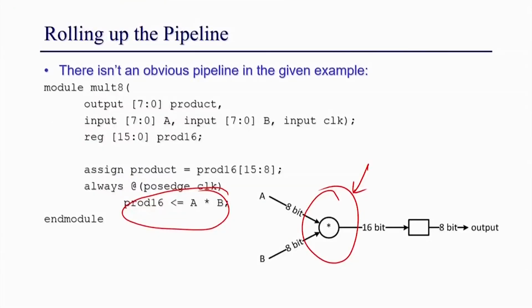This is also possible, and sometimes you have to do this kind of optimization just to achieve your target area, because maybe on your FPGA target your design does not fit. You need this kind of small change in your design so that the whole thing gets placed in your FPGA. In an FPGA the number of DSP blocks is fixed, and the LUTs and logic units are fixed.